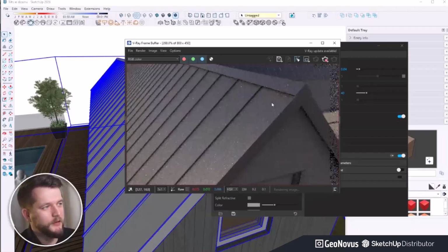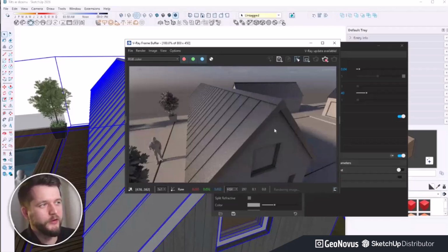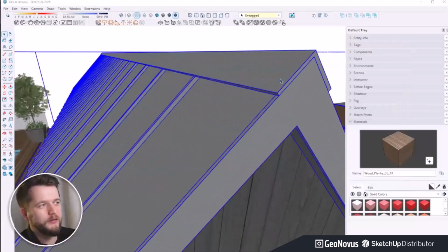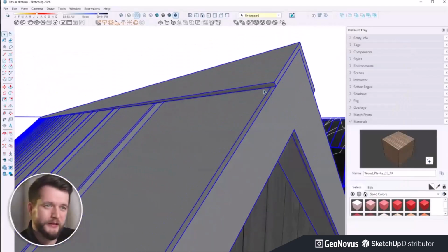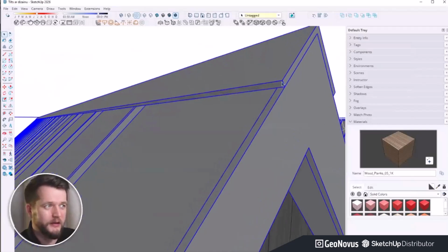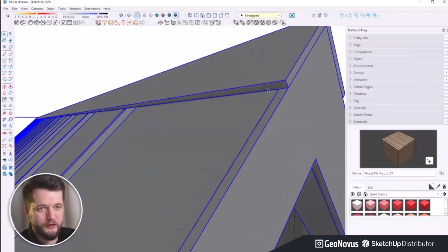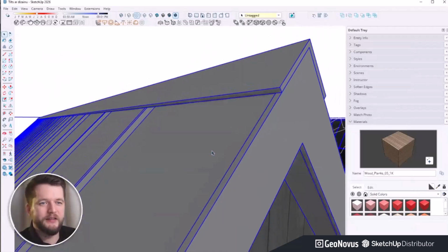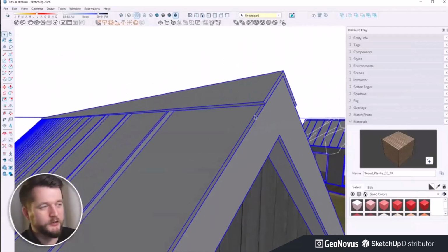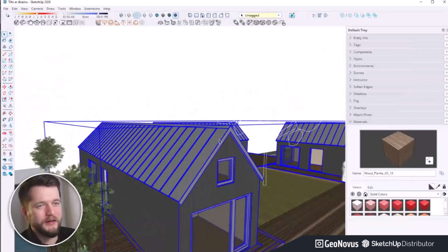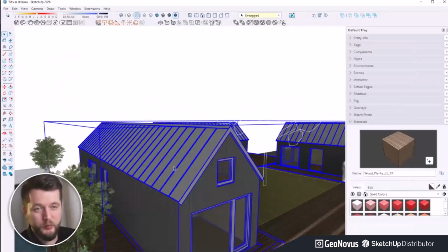There's at least proper reflections for this material. So you don't have to create anything from scratch, at least use this Chaos Cosmos material library. And for them to look more realistic, one problem for my model at least is all these faces, their corners are sharp. So adding some level of fillet and bevel to edges is gonna make any metal material look a lot more realistic.